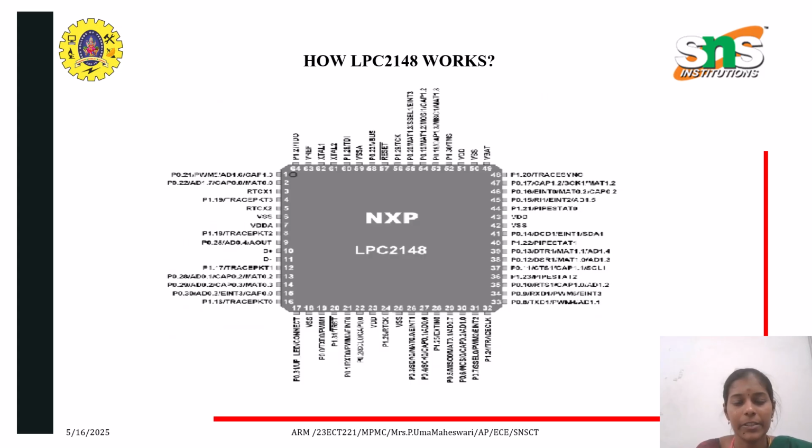This is called the LPC2148. This is from NXP. LPC2148 is an ARM7 TDMI-S based microcontroller with features like on-chip flash memory, static RAM, USB 2.0, serial interfaces, ADCs, DACs, timers, and so on. Everything is there.